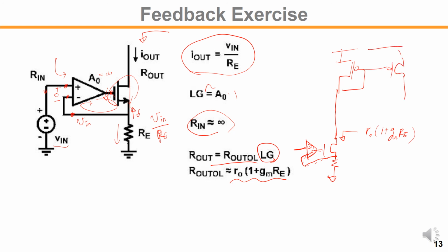The desired current level is set by this negative feedback, and that current level is replicated like that. This external VREF will be applied across the RE, so the current IRE would be set like that, right?